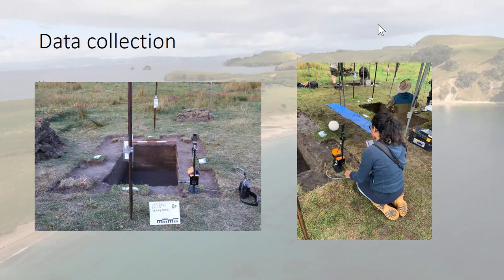So the SLAM, as I said, was done with the GeoSLAM Zeb Horizon. The 4 bases were positioned at the corners of the trench, and when every deposit was recorded, it was the 4 corners and then 1 in the middle of the trench. And we found that extra base in the middle of the trench was needed to really capture the walls to a point where they could be reconstructed. And finally, total station surfaces were recorded with the Trimble S7 robotic total station. The corners and sides of each surface were recorded, enough to capture the topography, and then about a 25 centimeter grid across the interior of the trench was captured.